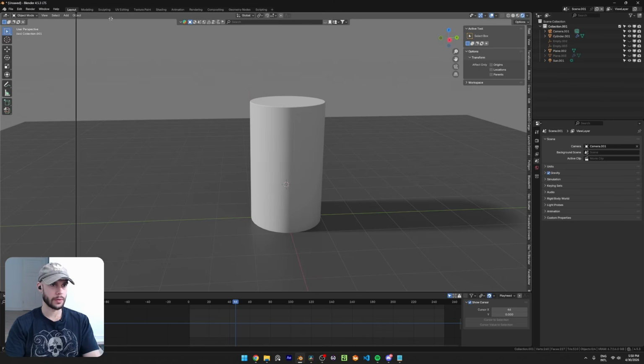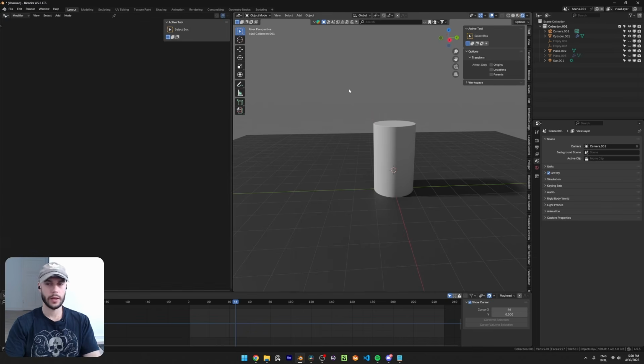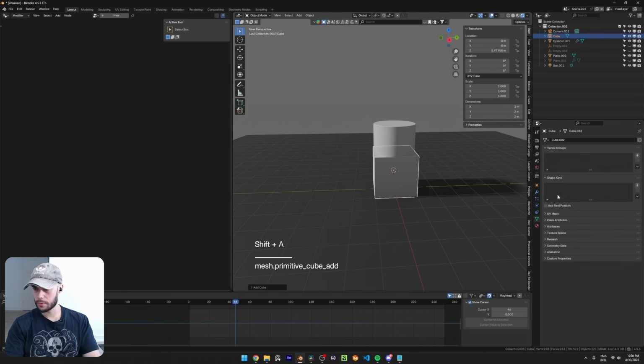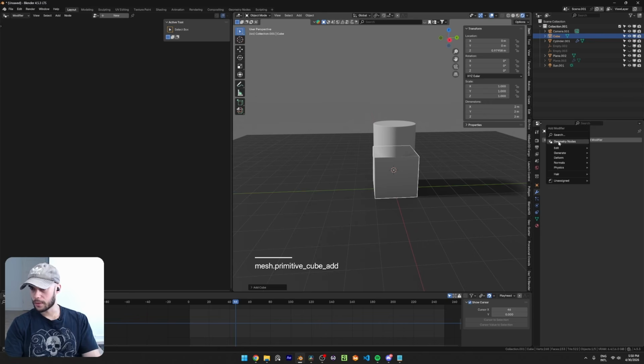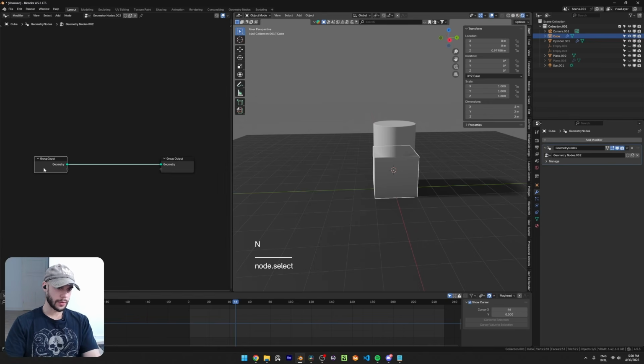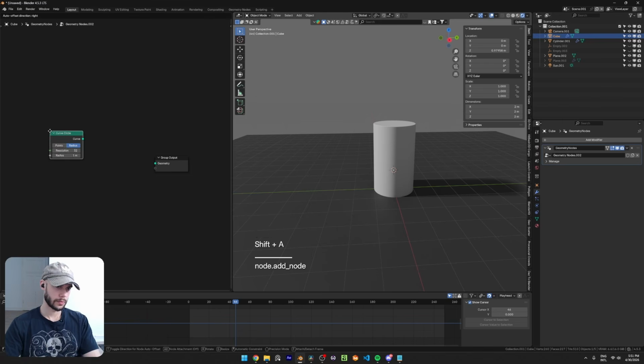So we're gonna open here a new window. Just go here to geometry nodes editor, and let's create, here it doesn't really matter, cube, modifiers, and geometry nodes, new, there you go. And here we can delete this because we're not going to use the geometry that we generated. We're going to generate our own using geometry nodes. So to start, we need a circle. So circle. So there you go.